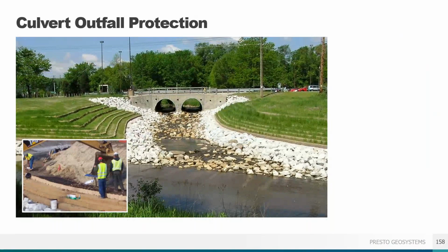If you want a vegetated channel but have strong flows, a pro tip is to include surface protection over your panels, such as a TRM or coir fabric like seen here. This is intended for short duration events rather than continuous flow.